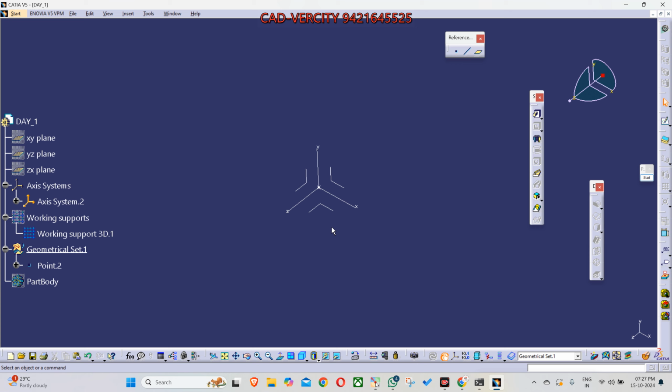Quickly. Holding the middle button and pressing the right button and moving the mouse inward and outward. Zoom in, zoom out. Hold the middle button and just click the right button one time. Click it. Don't hold the right button. Just click and release.